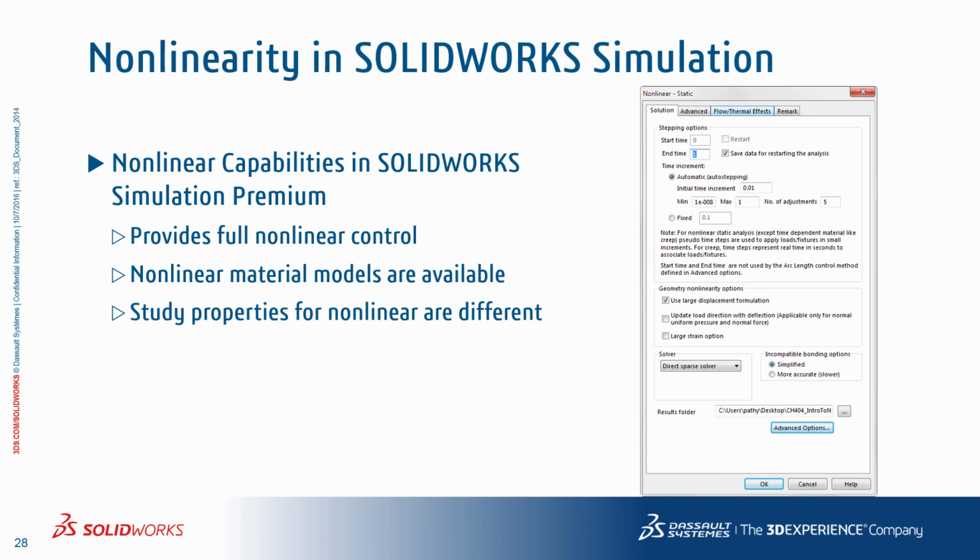To fully understand the benefits of nonlinear control, it is important to know that with all of the nonlinear modeling capability in SOLIDWORKS Premium and SOLIDWORKS Simulation Professional, only the final results are available. This may suffice for a system where the final response can be used to make a decision assuming the load is applied proportionally. But in scenarios that involve a non-proportional path for loading and also by using a nonlinear material, a full nonlinear solution is required to properly understand the system response from zero to the fully applied load, as the interim results may be needed to make the design decision.